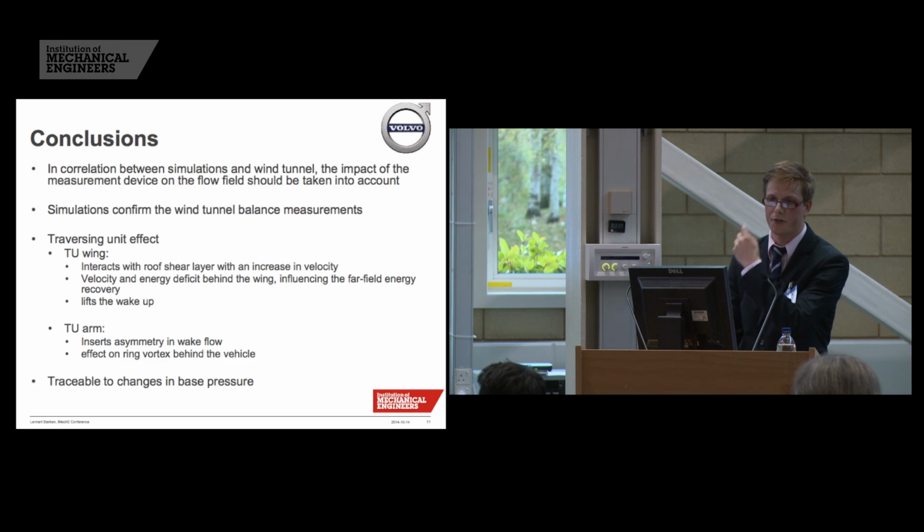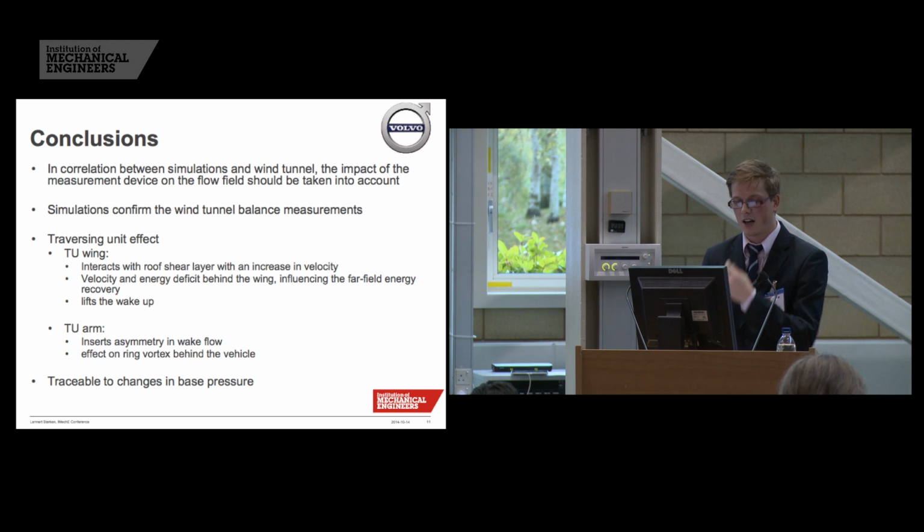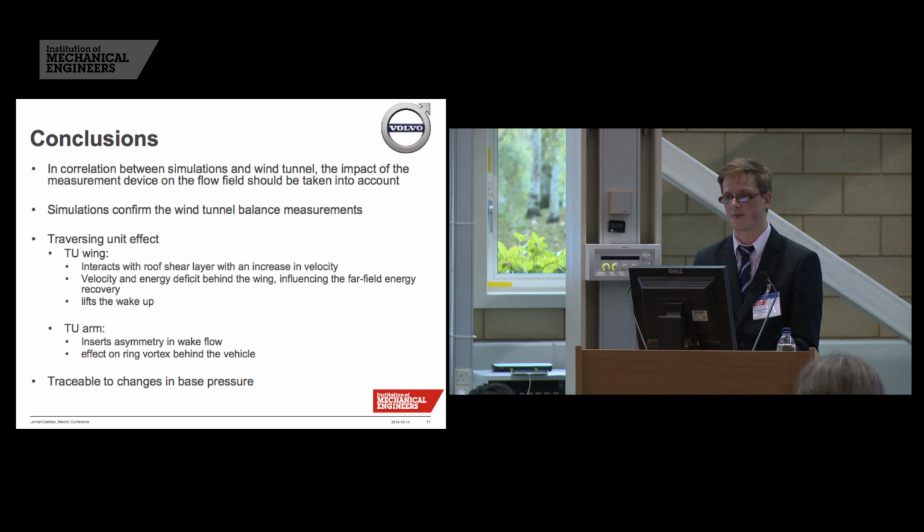If we then come to the conclusion, and maybe that could correlate to what was mentioned in the first presentation this morning, if we want to correlate wind tunnel results and results from CFD, we should also, of course, take into account that when we measure the wake flow in the wind tunnel, the device we're measuring with actually has an effect on the flow we want to know about as well.